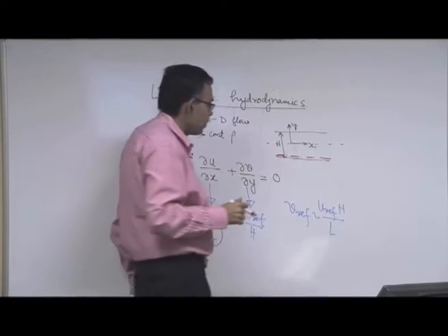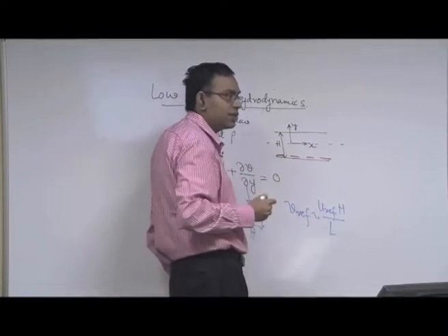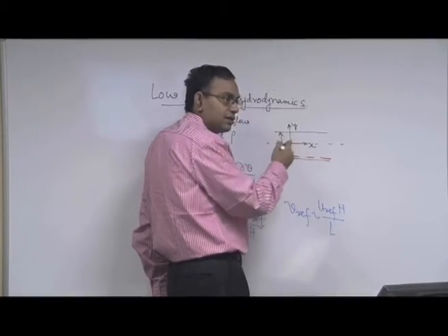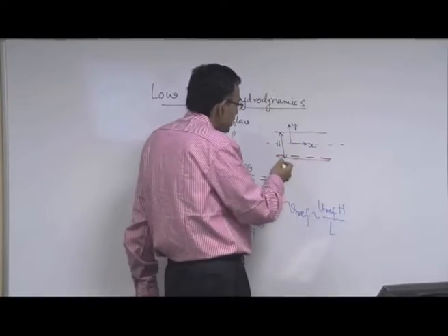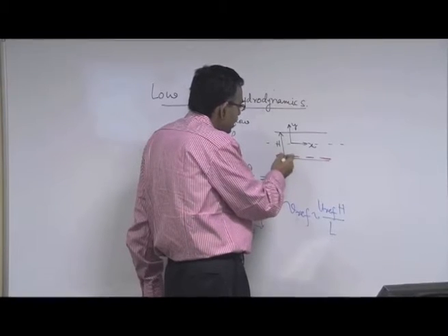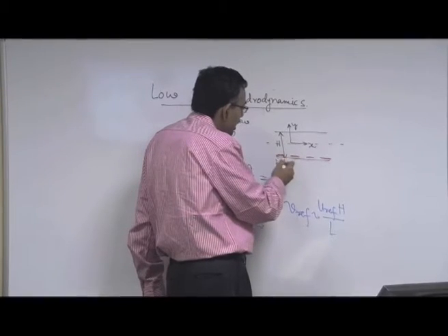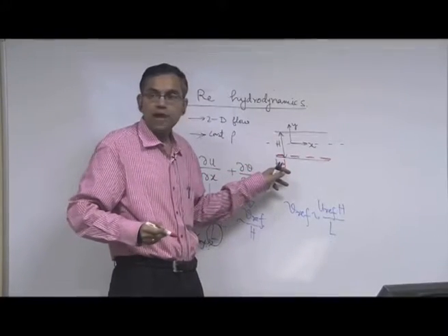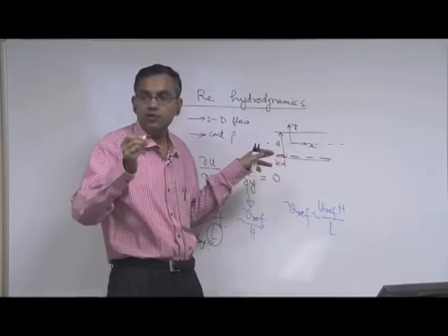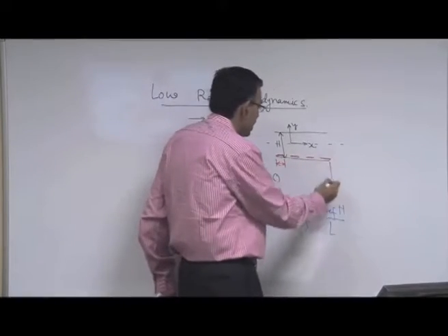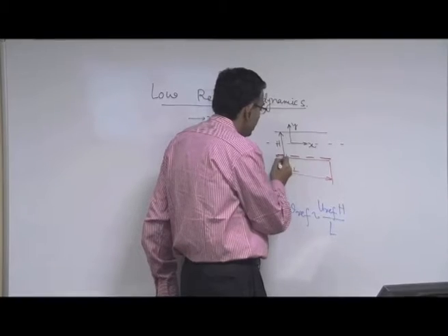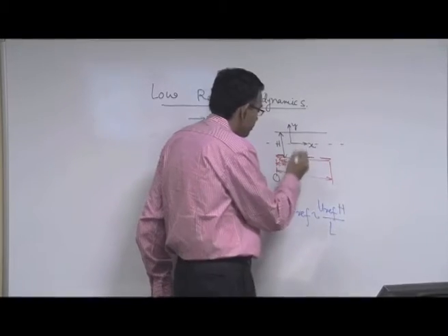Then if you pattern the surface with such patches, you can create local vortices. Now, if you pattern the surface with these patches, then the length scales of your concern are the span of these patches, not the length of your channel. So if the length of the channel is L, then this is actually your x ref.